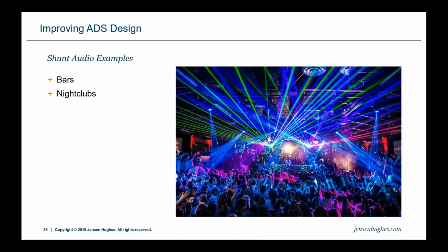Pre-COVID, nightclubs like this existed, and there's obviously no possible way you're going to see or hear a fire alarm signal in a location like this. We have to be able to do a lot of shunts in this scenario in order for everyone to understand what's going on. And the same is true for stages, for theaters, tenants in malls or in airports. All may have different scenarios, but providing shunts is important.